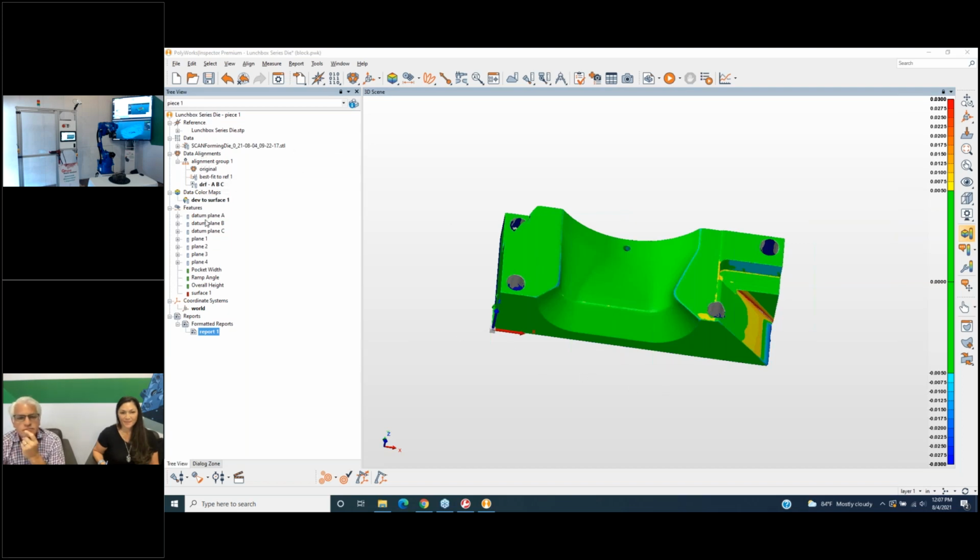This is a pre-setup report, very standard for PolyWorks, that we have automated the files or the STLs from the Creaform HandyScan Black Elite to just come in and automatically run a report. So it happened faster than I could switch my screen. So I have an additional format STL file that I'll show you and just manually replace it. But once this is done, it sends the yes, no signal.